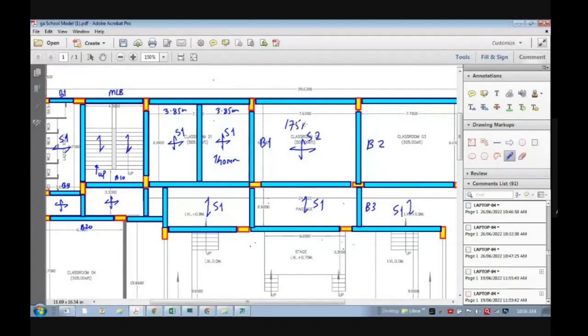So whenever you go more than 150 mm thickness, generally there is a possibility of serviceability issue, and possibly you should try to avoid such things. But you can still do this design also. Now these are the two cases I can say.